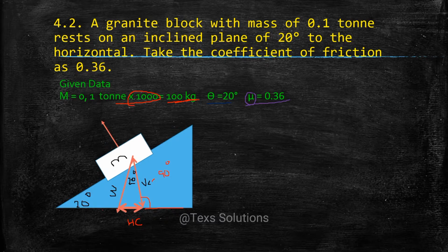So the next one is, this is the plane, and I have the horizontal components also moving with it. Okay, and they are adjacent to each other, so this is known to be parallel. So the vertical component is perpendicular to the plane, while the horizontal component is parallel to the plane. So this object needs to be in equilibrium. I have a vertical force coming down, so I have a vertical force going up.